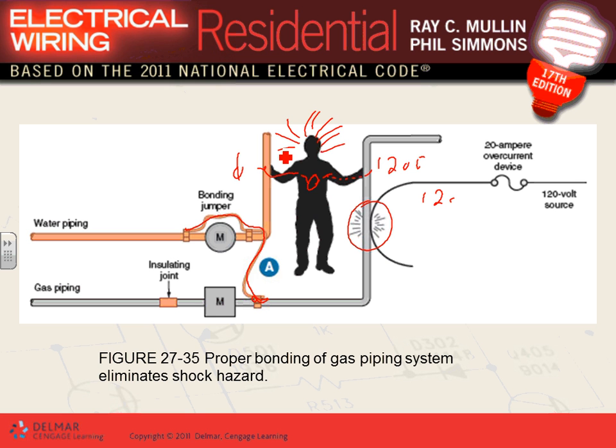Can you guys see that? Now, if you put that wire here, guess what's going to happen? Now, this is at 0 voltage. This is at 0 voltage. What happens when you put a 120 volt and 0 volt together? Short circuit. That's ground fault. That's called ground fault. This fuse here will say, you can't do that.